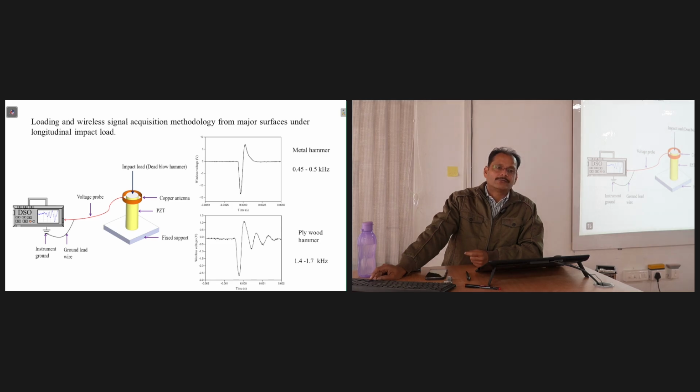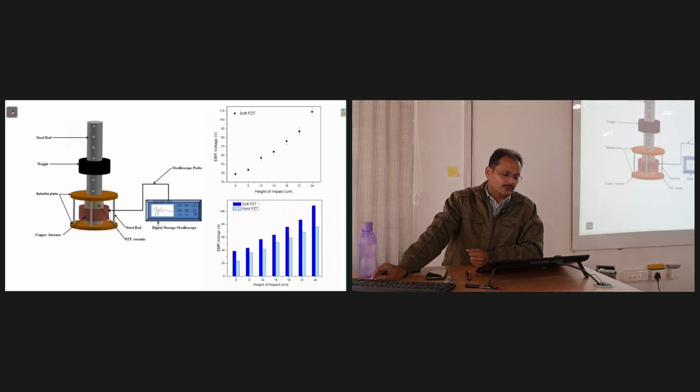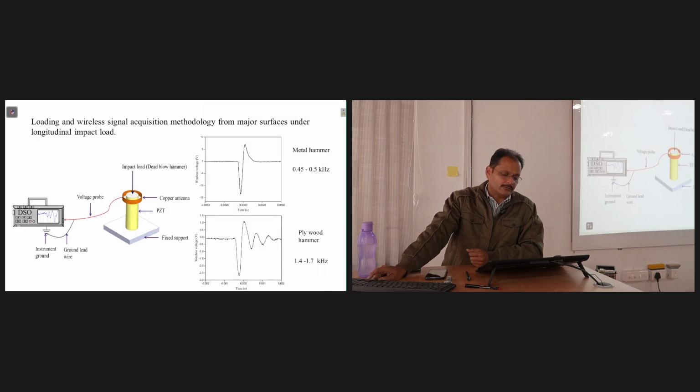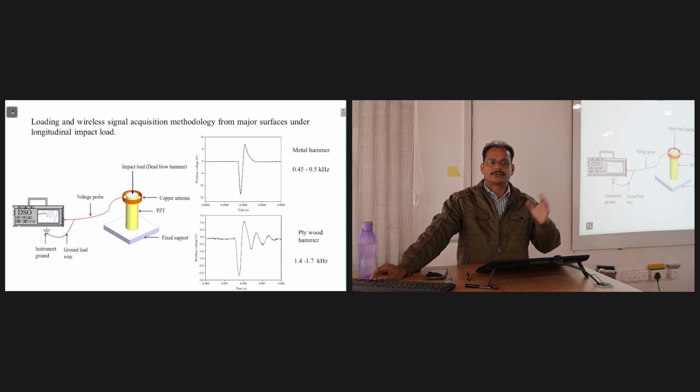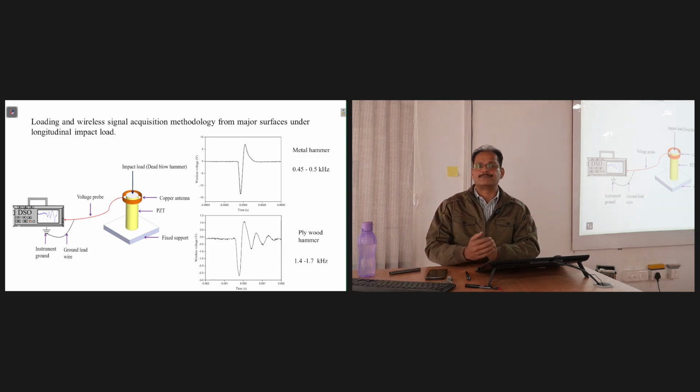These had a 15 mm height but 6 mm diameter. These we had bought, we did not make them. The PZT we had bought ready made. The sample sizes remained the same. The PZT is always 6 mm diameter and 15 mm height. For both, only the setup to apply impact changed, but the size of the sample remained the same.